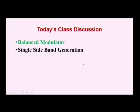Welcome to UGC lecture series, Communication Electronics for Applied Electronics. In the last session, we discussed how to generate an AM wave and then how to detect the AM wave. That is, we generated double sideband with full carrier. In today's session, we are going to see about the balanced modulator and then single sideband generation. The balanced modulator is used to generate double sideband with suppressed carrier.